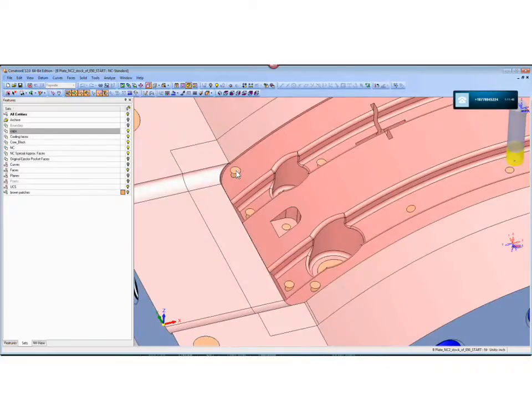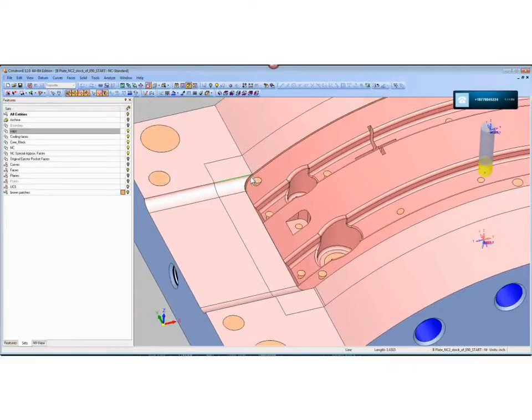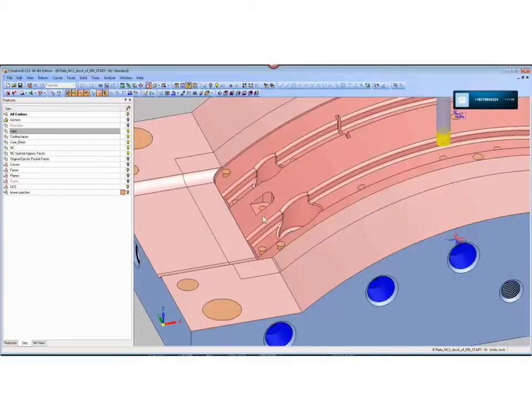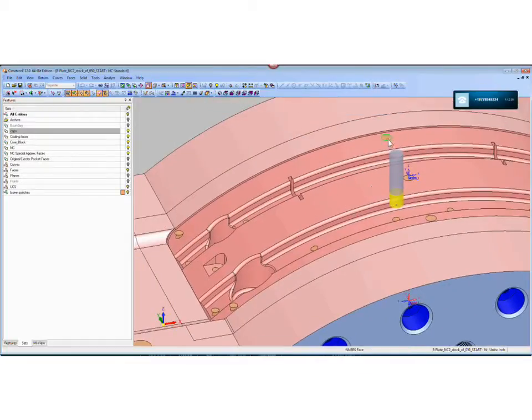So here I'm going to show again how I set up logic, and I said that if you have a breach condition, I want to do circle milling down to the top of the hole. And if you don't have a breach condition, or if that breach condition is, say, less than 50 thousandths, then don't circle mill it. So one sequence is it's either going to drill this hole and circle mill it first, and it's all dependent upon conditions and logic. So let me go back, and we'll process it, and I'll show you the result.